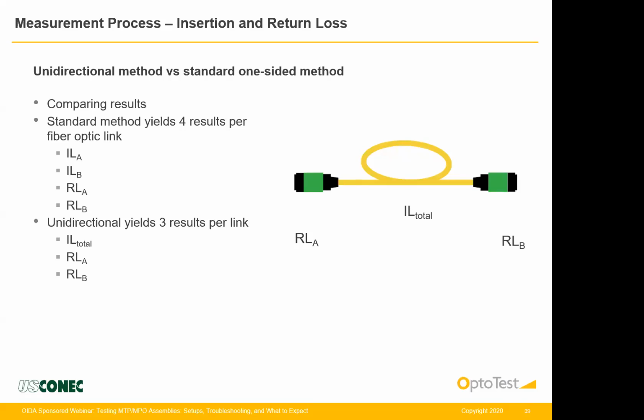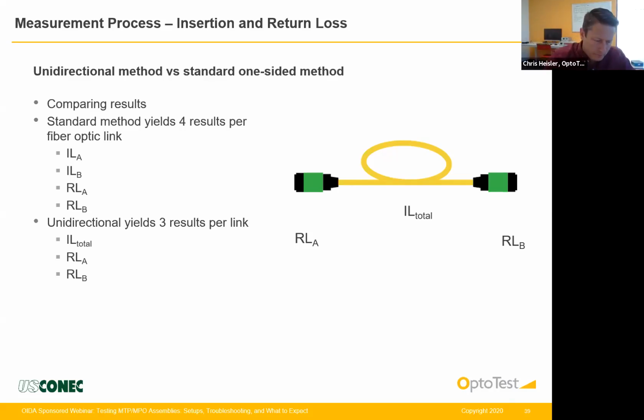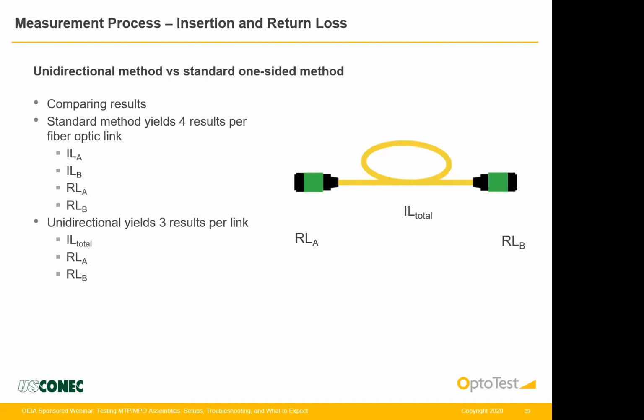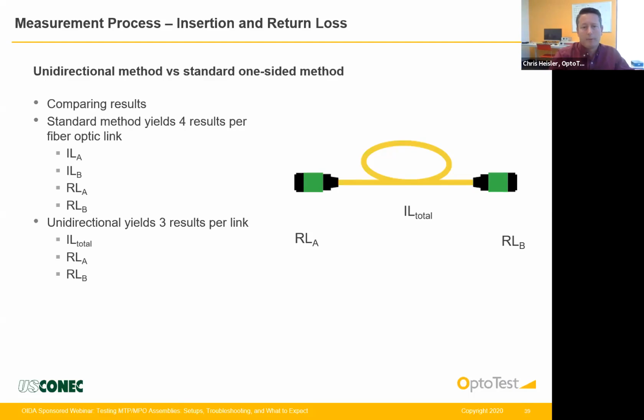Is the TDR technique useful for multi-mode fiber as well? Oh, yes. The time domain method is good for multi-mode fiber as well. We presented mostly single mode setups here, but for multi-mode assemblies, the pulse-based method is perfectly fine as well.